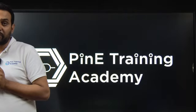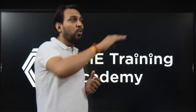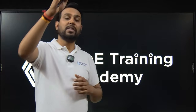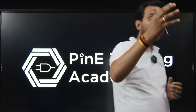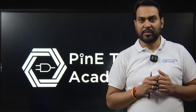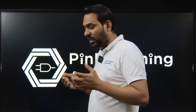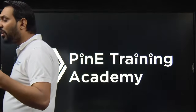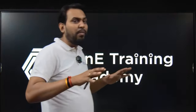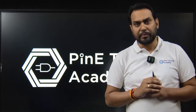They also degrade your performance in terms of gain. Let's talk about the Bode plot. You have a DC gain, and after some frequency it decreases. What is happening? Basically, the parasitic capacitance comes into effect at high frequency and decreases your gain. Similarly, the inductance is very small because it has a very small value, so we are not talking about the inductance, and we can eliminate this part. We only focus on the resistor and capacitor.